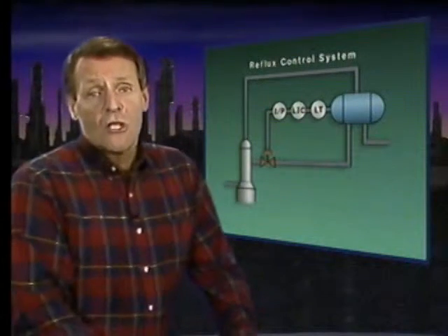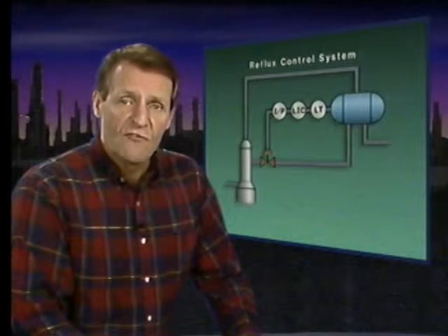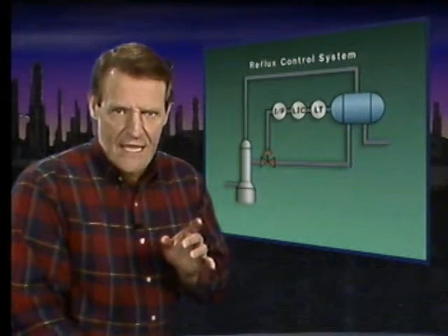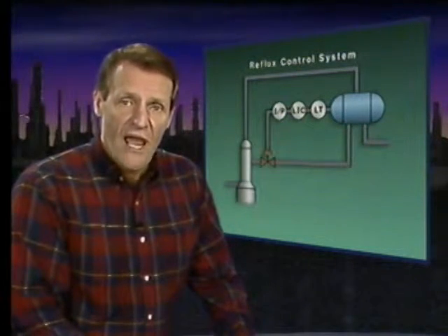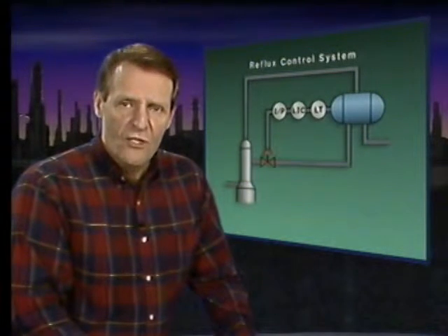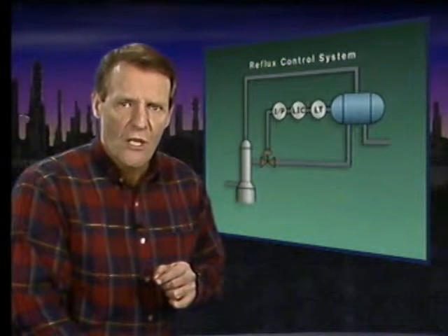In some cases, you can eliminate possible causes of a problem faster by using a method called half-splitting. This method splits the process in half and reduces the remaining number of possible causes by half. We'll use a reflux control system for a distillation tower to show how this method works. We'll start by looking at the system.